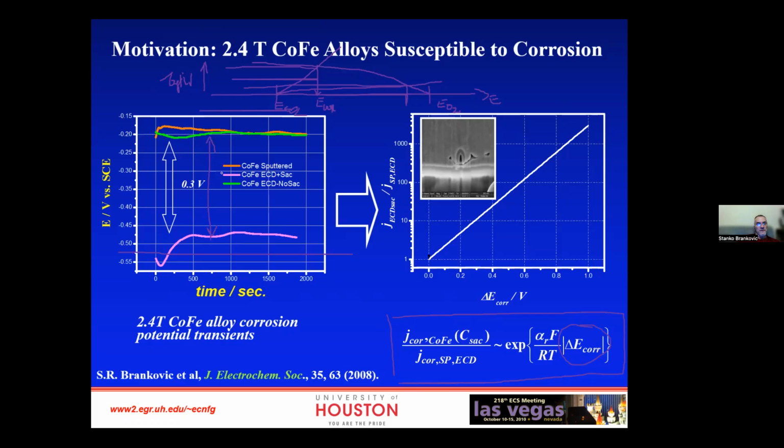And this is a very big problem because, yes, we do get benefit of the additives for many properties, but look, if you just play with this, you will realize that this is going to corrode 10 times faster just because the alloy is electrodeposited with the presence of additives.